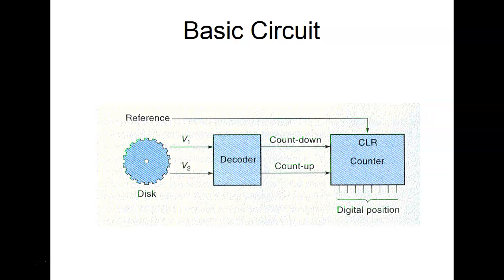And a quadrature incremental encoder will not only give us position, but also direction. So now we know the position of something, whether it's left, right, or right, left, or up or down. So odds are, the encoders that sense position are going to be quadrature encoders.